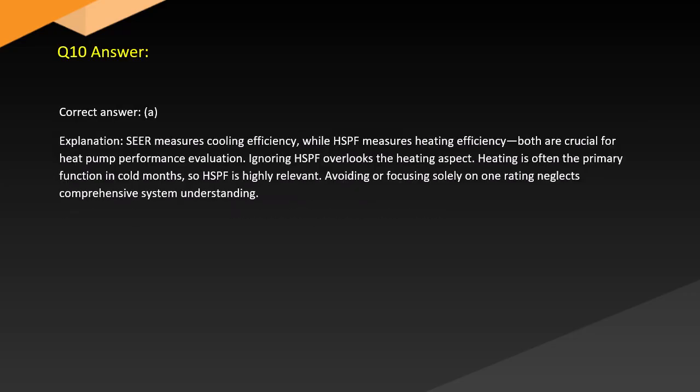Answer. Correct answer, A. Explanation. SEER measures cooling efficiency, whereas HSPF measures heating efficiency. Both are crucial for heat pump performance evaluation. Ignoring HSPF overlooks the heating aspect. Heating is often the primary function in cold months, so HSPF is highly relevant. Avoiding or focusing solely on one rating neglects comprehensive system understanding.